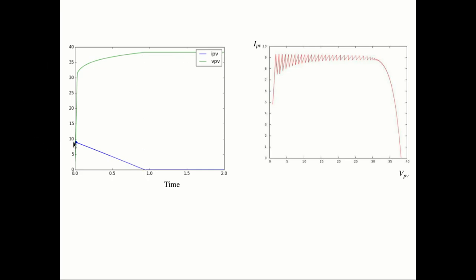So you see, this is short circuit: voltage is almost zero, current is near the short circuit value, and this is very important. The current is at the short circuit value, it's not dangerously high. In a battery, this would be dangerously high, which means it could damage the battery. Short circuit, but with a PV panel, not so. As we increase the resistance, the current decreases, voltage increases, and somewhere here would be the maximum power point.